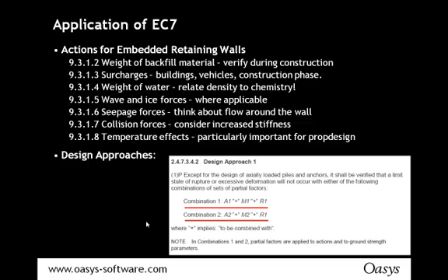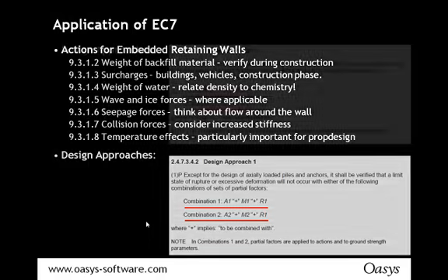But here, for example, in Eurocode 7, in section 2, they give a detailed breakdown of the design approaches and the combinations of partial factors required. So within design approach 1, you've got 2 combinations of partial factors. It's combination 1 and combination 2. So combination 1 and 2 are covered here, and you can see it from the excerpt from EC7.